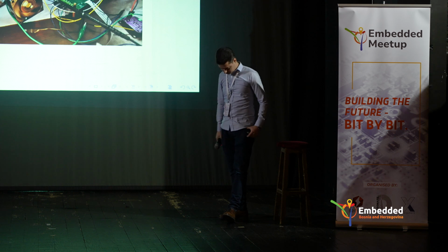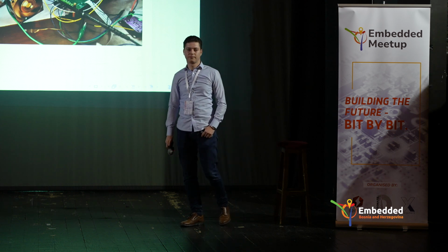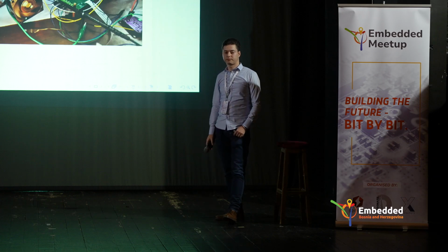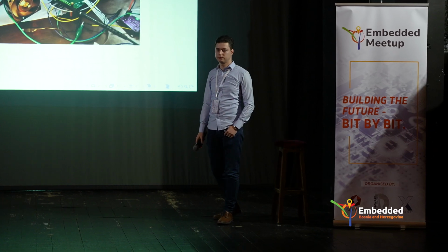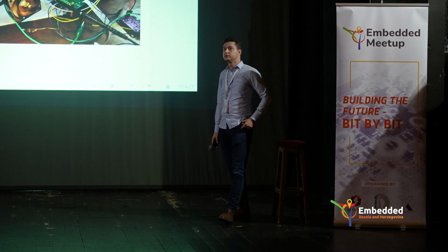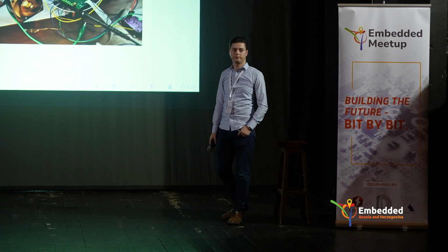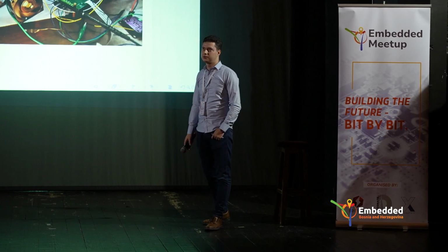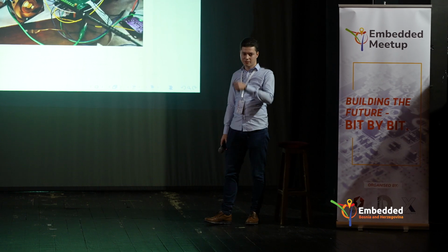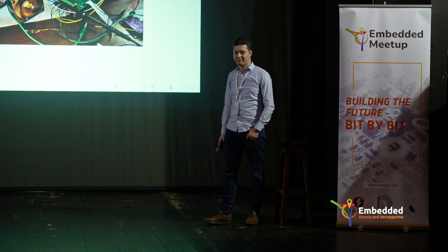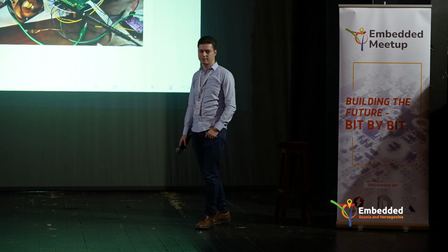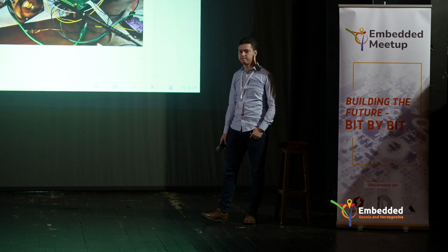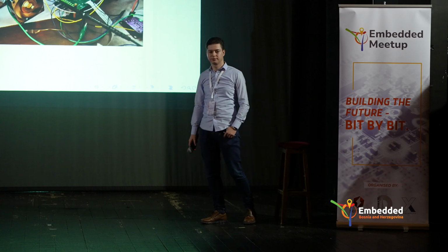So we cannot add a breakpoint and see what's happening. This needs to be orchestrated in a really synchronized manner, and for the only way to measure something, even placing debug messages can introduce delays and false information that will lead you to incorrect conclusions. The only way is using external instruments, basically, and flipping GPIO pins when certain operations start and stop.